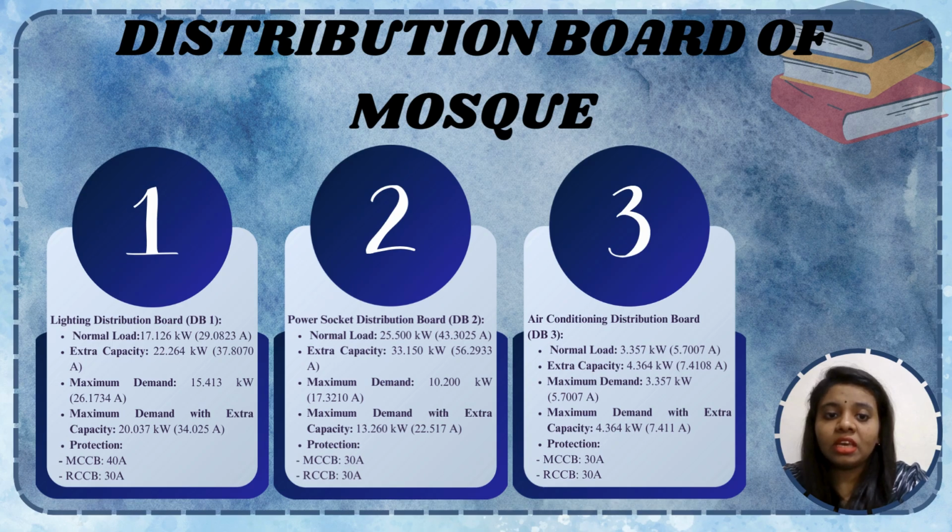The third one is the AC power socket DB, designed for a load of 3.357 kilowatt and 5.7007 ampere with the extra capacity up to 4.364 kilowatt and 7.4108 ampere. The maximum demand remains steady at 3.357 kilowatt and 5.7007 ampere, rising to 4.364 kilowatt and 7.411 ampere. It's also protected by a 30 ampere MCCB and RCCB.